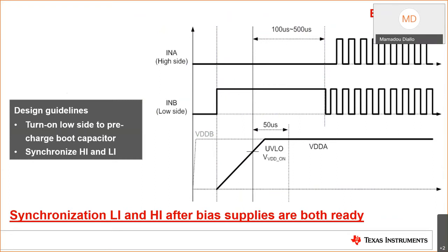The figures on the right show power up UVLO delay timing diagram for input and VDD supply. It is necessary to synchronize the input signals only after the bias supplies are both ready. This example shows sufficient margin where the PWM signal are launched well after the driver supply has crossed the UVLO threshold.